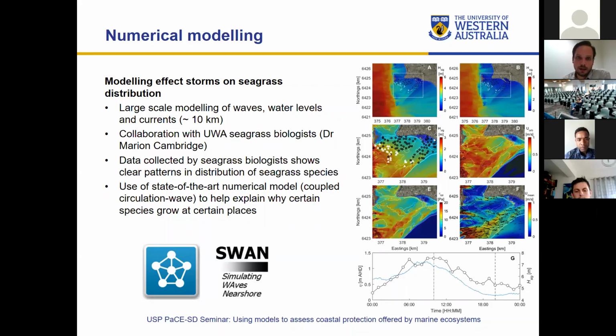So then we got together and talked about how we could try to solve that. So we ended up running a coastal hydrodynamics model, Delft3D, coupled with a wave model, SWAN. And we actually found a really clear relation between the wave heights that are found in areas with specific species, and that turned out to match with results from other studies on the roots, for example.